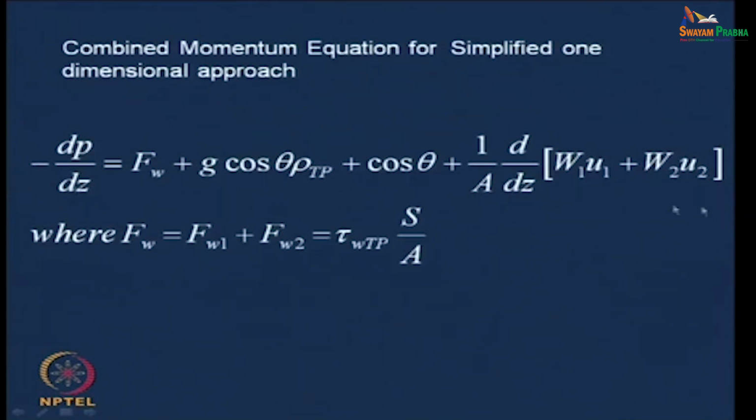If you observe this form of the equation and the homogeneous flow model we had developed, the only assumption we relaxed was that the two phases were allowed to have different velocities. Other than that, this expression is identical to the one derived for the homogeneous flow model.